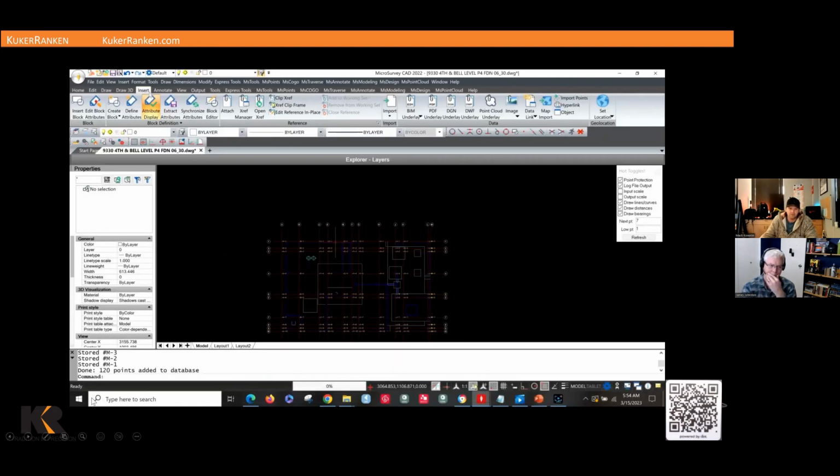All right, import control and Align. Before we let this go, I am used to using Align. Now, MicroSurvey CAD offers the RCS, right? Rotate, translate, scale. It's a powerful tool. I'm used to using Align because I like to know that I'm not altering the scale of that control I got from the surveyor. I'm eliminating my error from it.